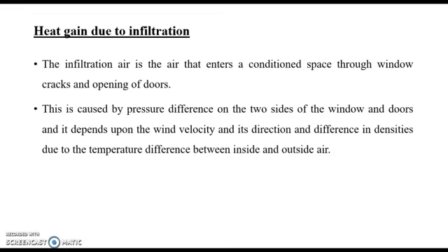Due to these cracks and openings, and the air pressure difference, air enters from outside to inside of the conditioned space. The reason is the pressure difference on two sides of the window and doors, and it also depends upon the wind velocity and its direction, and the difference in density due to the temperature difference between the inside and outside air.